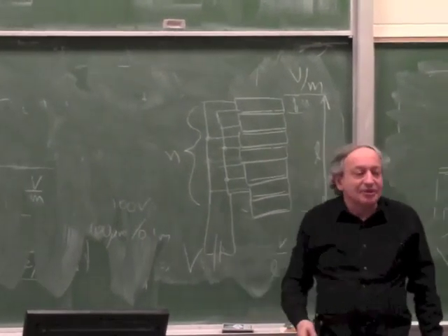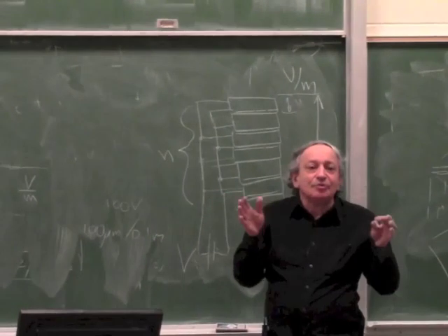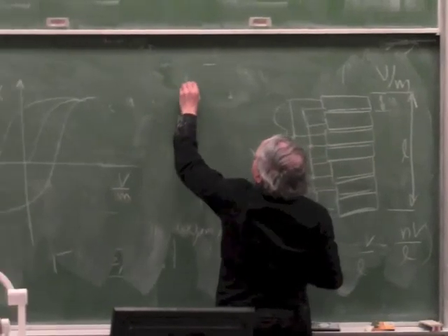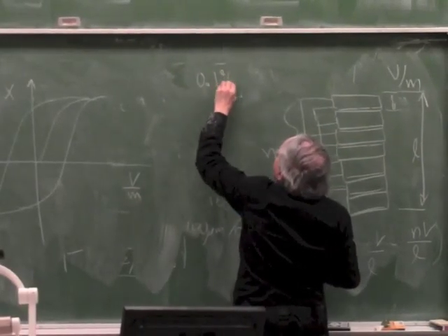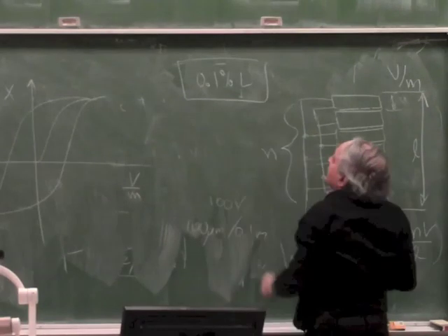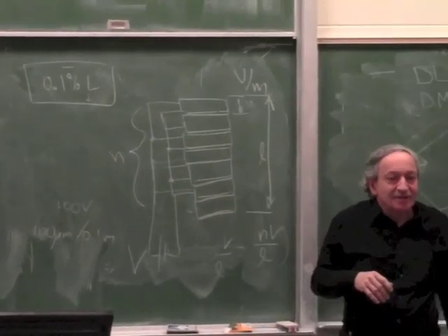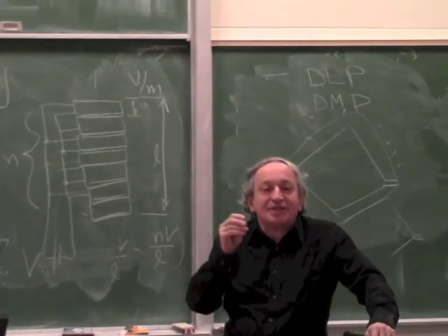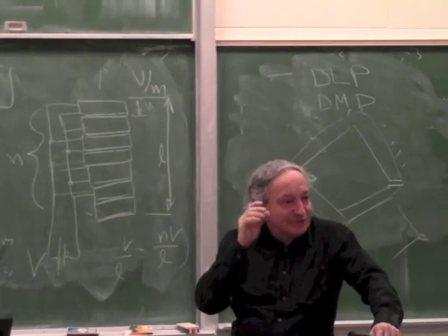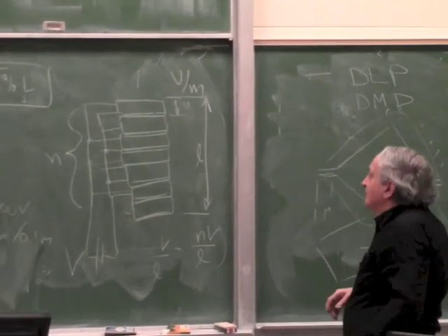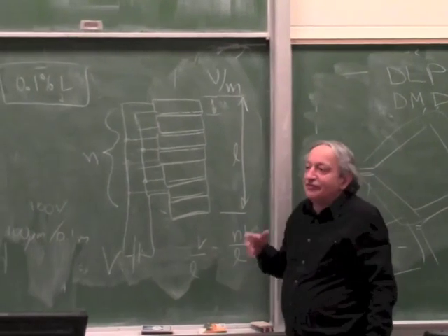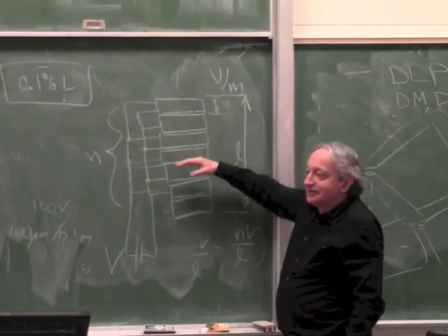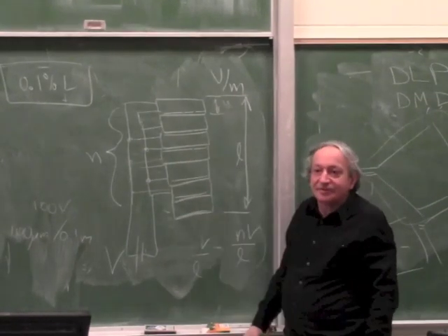It's also 100 micron. Another way of saying it: the maximum movement of all these magnetostrictive actuators and piezo actuators is about 0.1% of length. And that's it. Okay? Compared, say, to an electromagnetic actuator, which can move 50%. So the movements are very small. Okay, so the first problem, the need for a very high electric field, is solved by cutting into layers. So you increase the electric field.